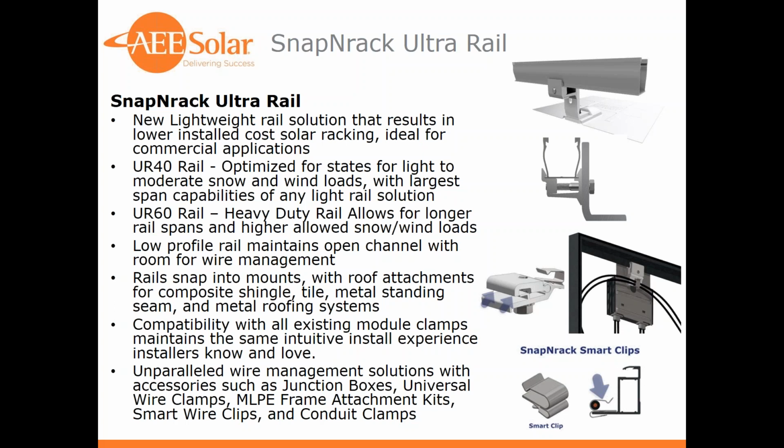So if it's a pitched roof or if it's a penetrating roof system, we have a UR40 rail that's optimized for states with light to moderate snow loads, and it has a very large span capacity compared to other light rail products on the market.